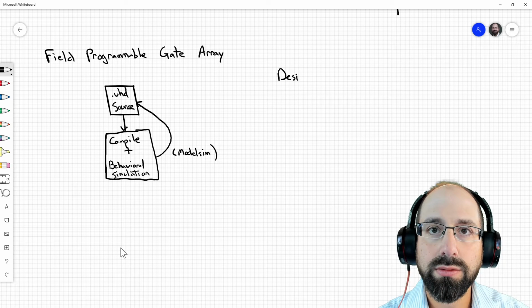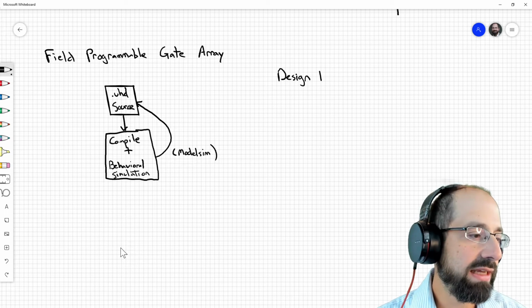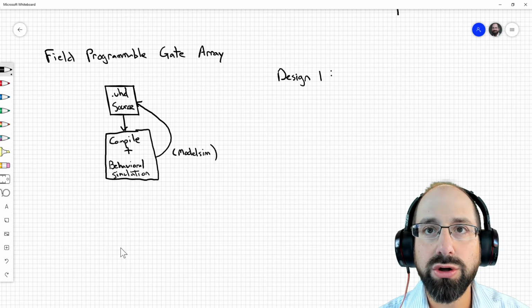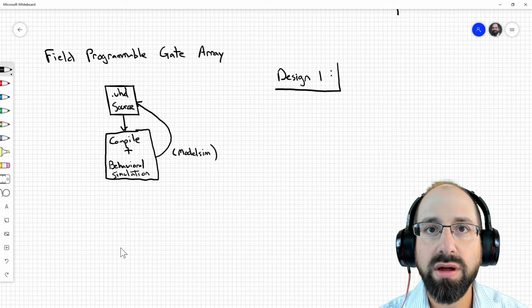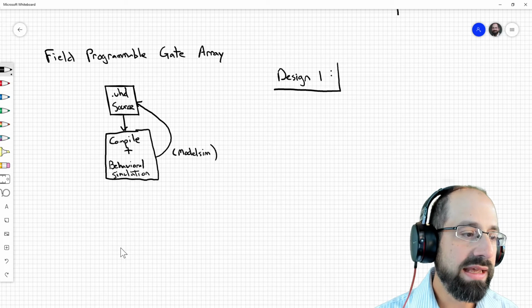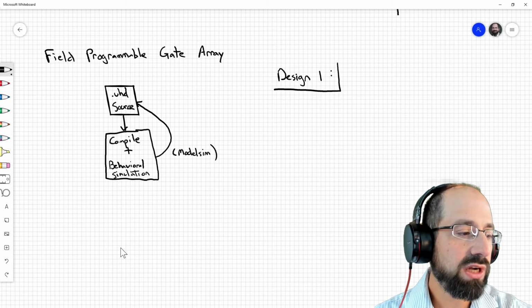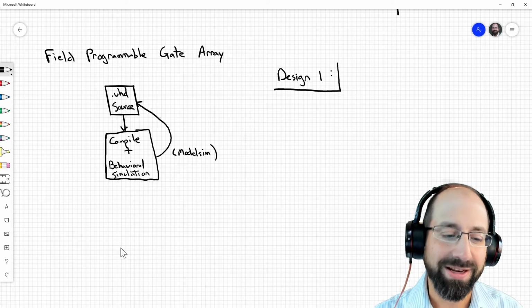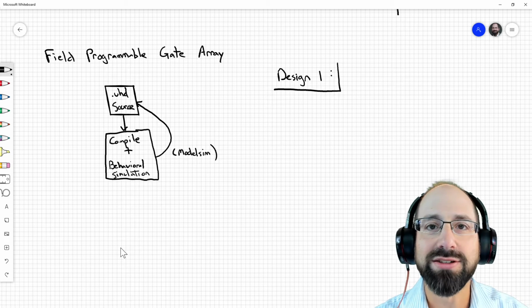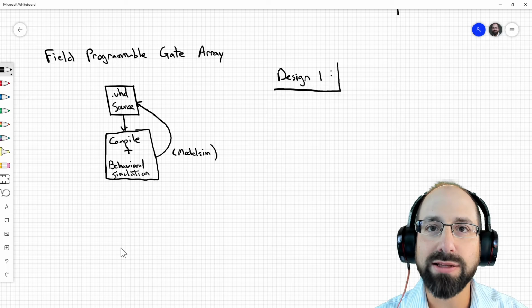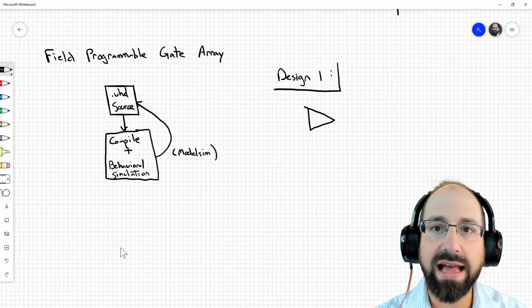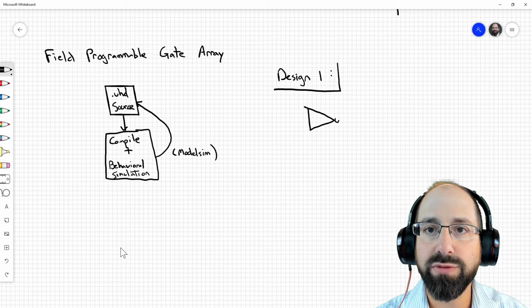So for design one, if I were to draw this, and there are some different ways one could draw that design, even given the same understanding of what it's doing, we recognize that there's an input switch coming in. There's a clock. We didn't actually use the reset at all. We could have reset it. There's nothing wrong with doing that, but it's also probably not super necessary. So this design one has the switches coming in, and I would just draw that as an input vector, which we called SW for switch, and it was an 8-bit value.